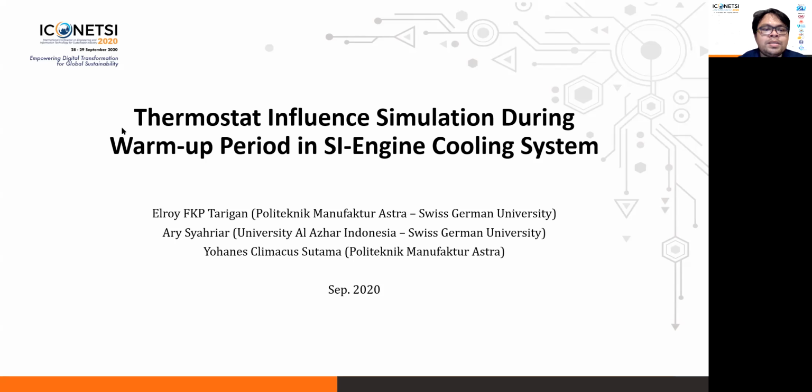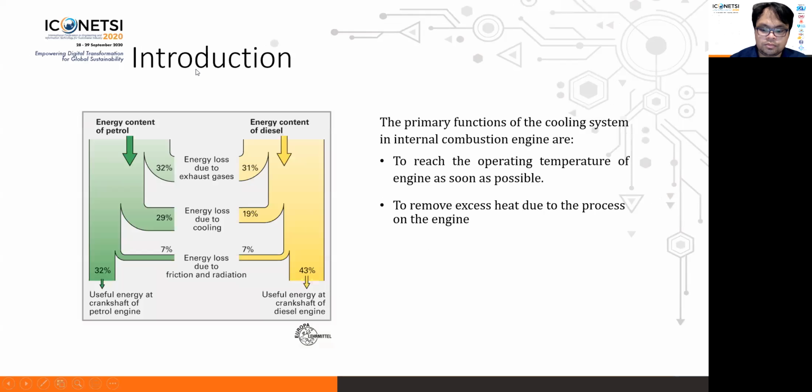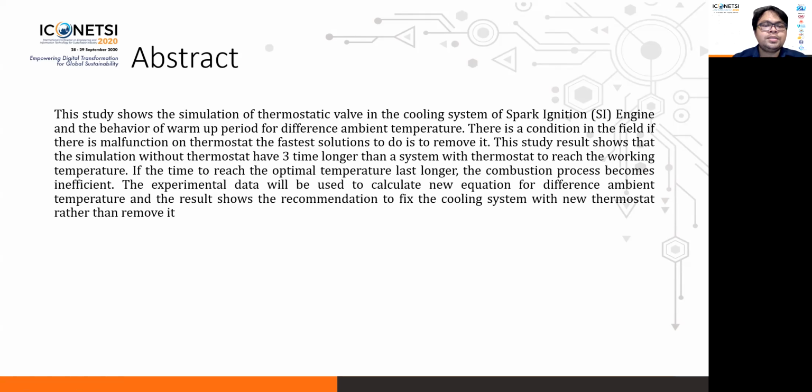So my theme is about the thermostat influence simulation during the warm-up period in the spark ignition or gasoline engine cooling system. The study shows the simulation of the thermostatic valve in the cooling system of a spark ignition engine and the behavior of the warm-up period for different ambient temperatures.